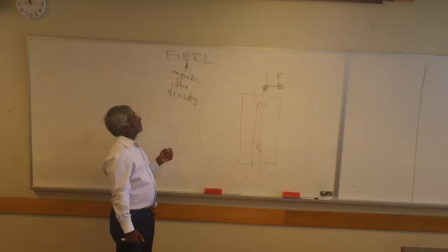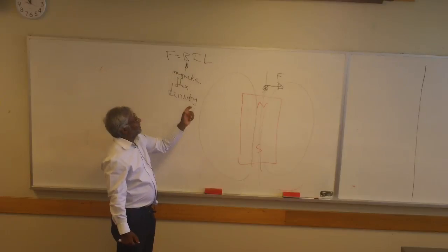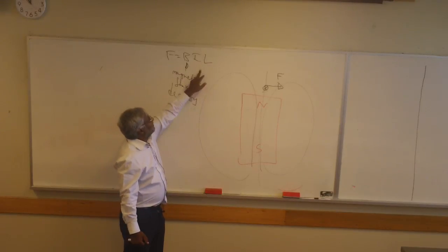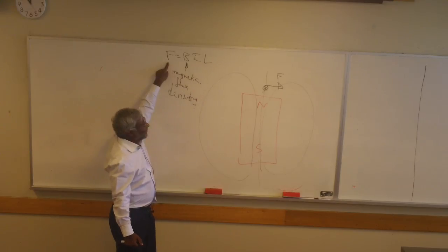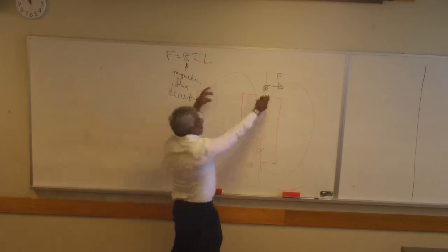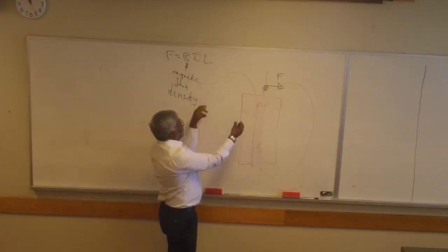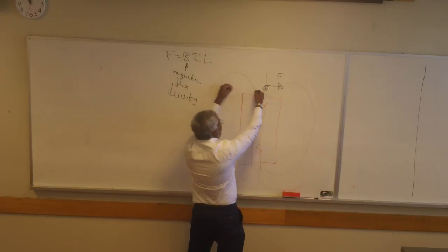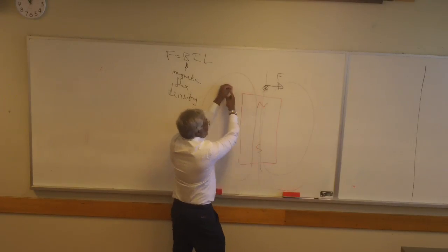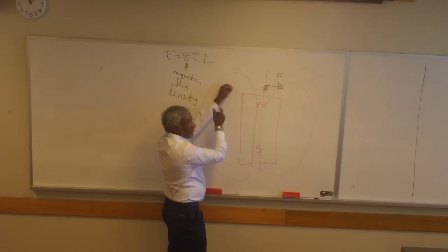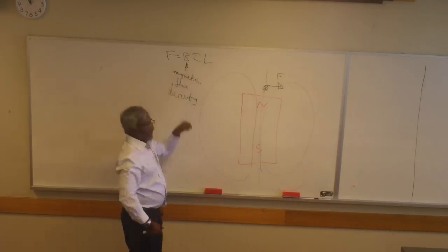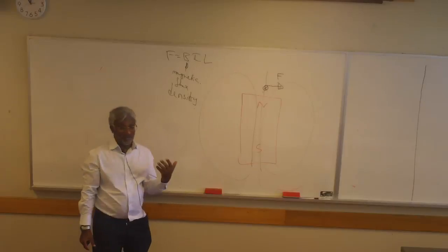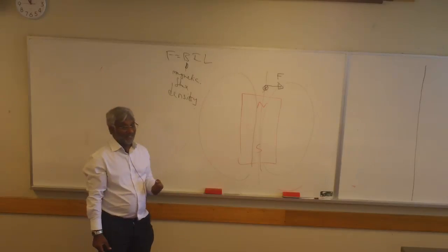So if I wanted to measure flux density, I'll have a piece of conductor of length L. I put 1 amp in it, and I measure the force, because I could have a spring balance on this side here. Switch on the current, it will pull, and my spring balance would tell me what the force is, and I'll be able to get the flux density. So I have a very good concept of what flux density is.